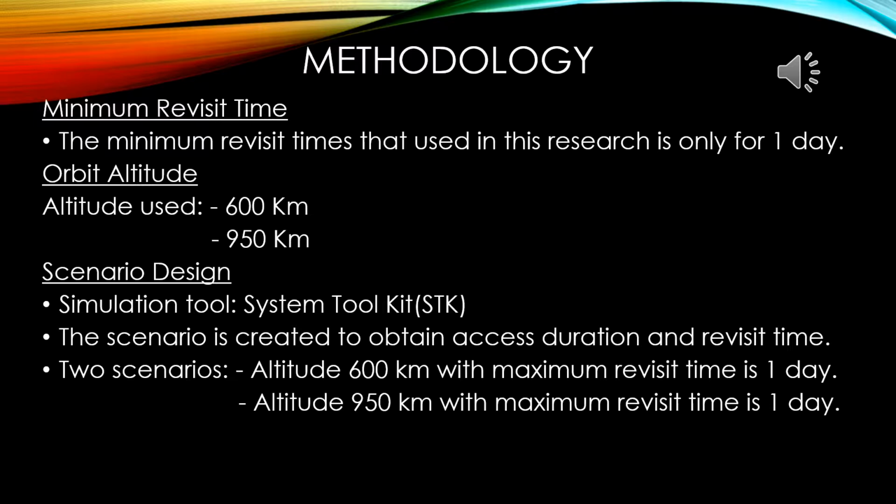The scenario design. The simulation tool that we are use System Toolkit or STK. The scenario is created to obtain access duration and revisit time. There are two scenarios that we use in obtaining the result. First, the altitude in 600 km with maximum revisit time is 1 day, and the second is altitude 950 km with maximum revisit time is also for 1 day.